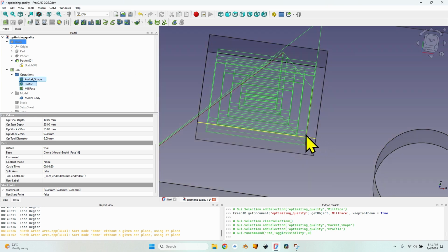I can make a final pass on the outside with the total cutting height of the tool bit engaged, because it's just a little pass, and after making all of that I can mill the bottom of the pocket. In my situation on my machine, the last operation, the mill face, is not really necessary because the Z-axis is pretty stiff and the profile operation won't leave too many, too visible grooves on the outside.